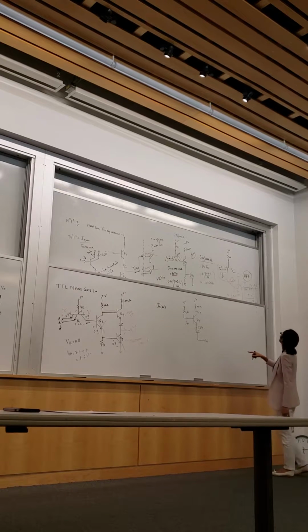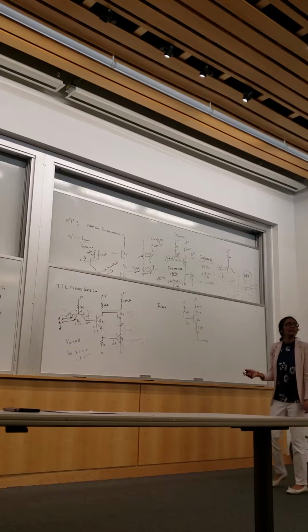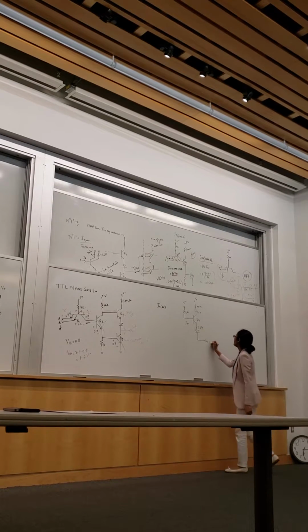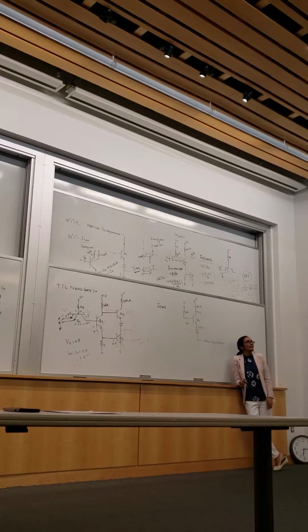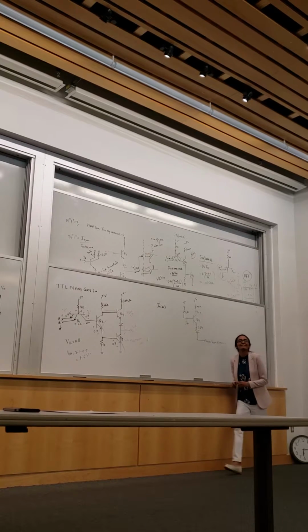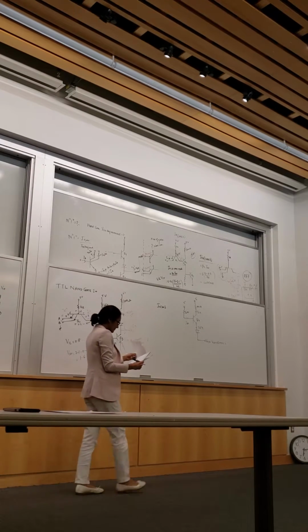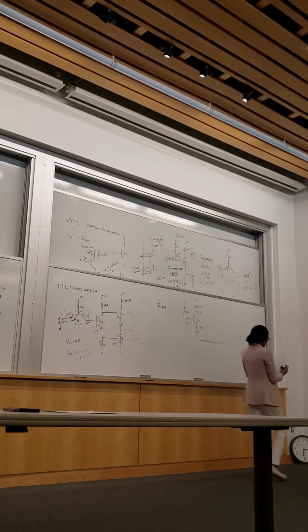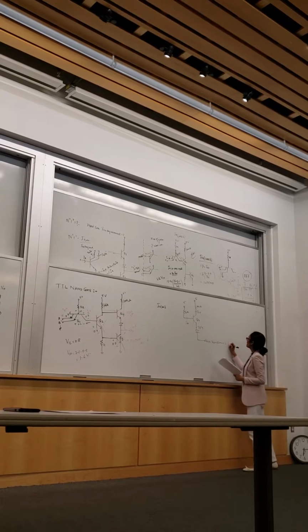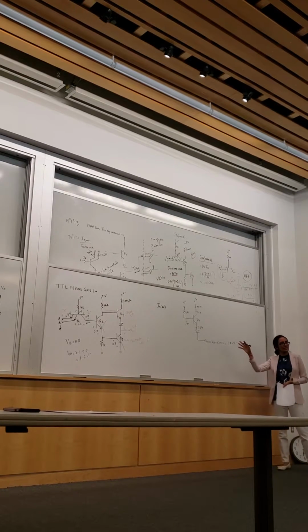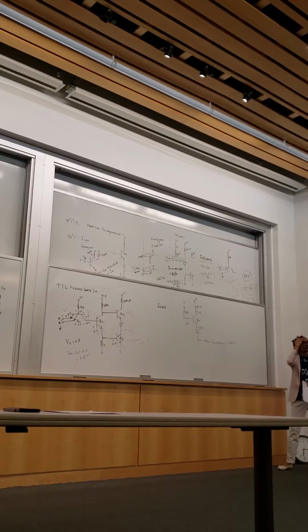And is V naught any noise margin given in the problem? I think there was. What was the noise margin? 150 millivolts? Yeah. And then your VOH will become VIH plus 150 millivolts. That's going to give you 1.75 volts. You guys understand this circuit? Okay.